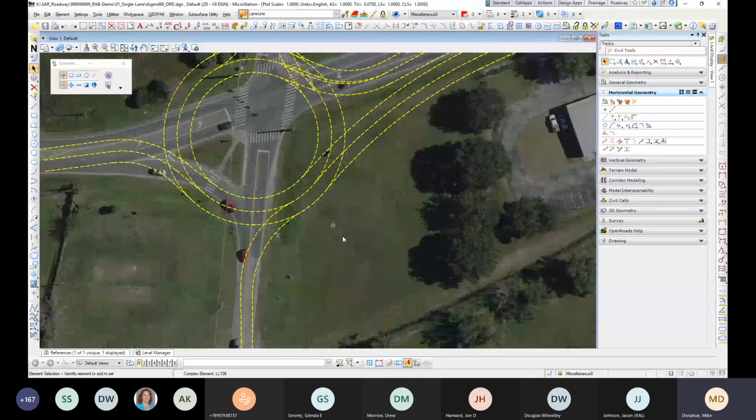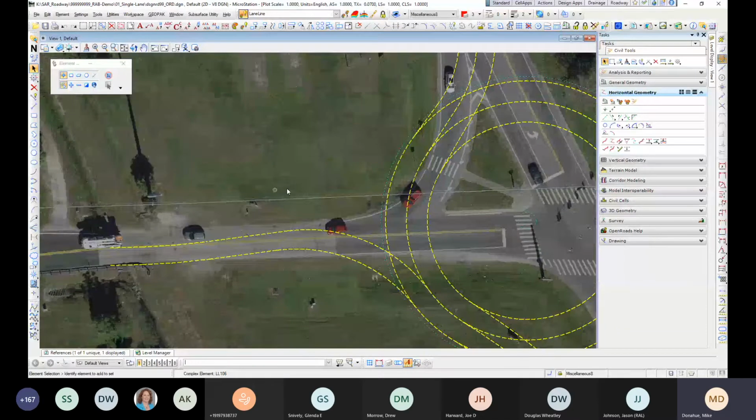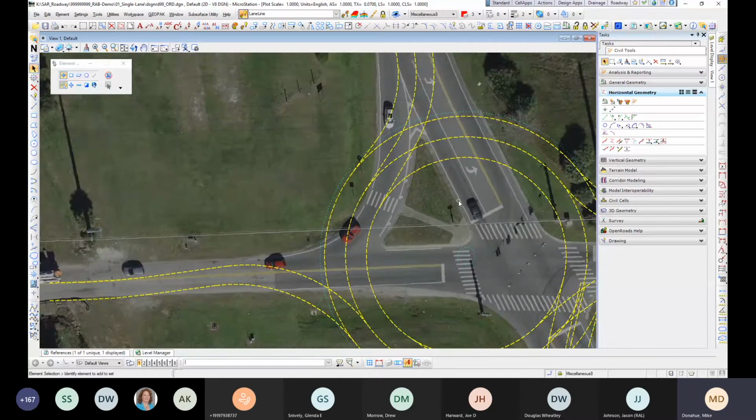Yeah. And now we'll look at the exit movement. Again, the exit is going to likely come off of this left turn that's going to spiral just a little. It's not going to be a true spiral in the sense that I won't bring it out here and push the whole roundabout out. You can absorb that in the island, and I'm at 12:30. I should have time to show you how to do that. I don't do that really in this environment, but I want to show how you export this and clean it up pretty quick once you're happy with the concept.